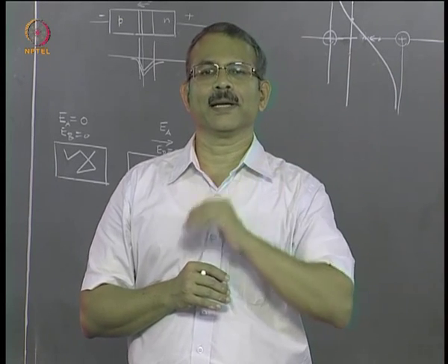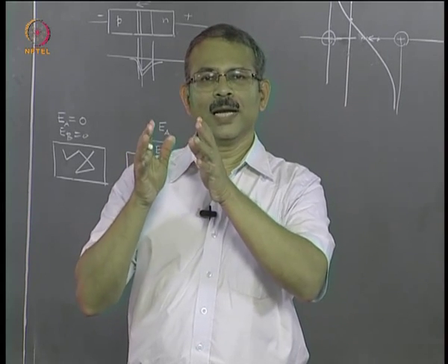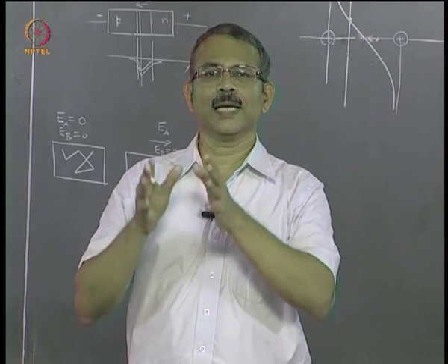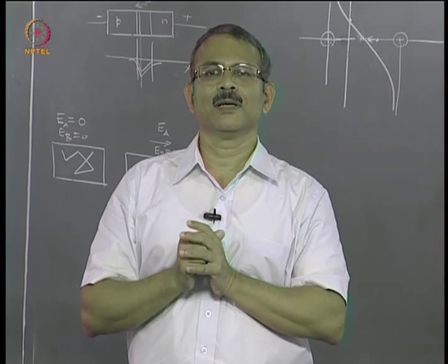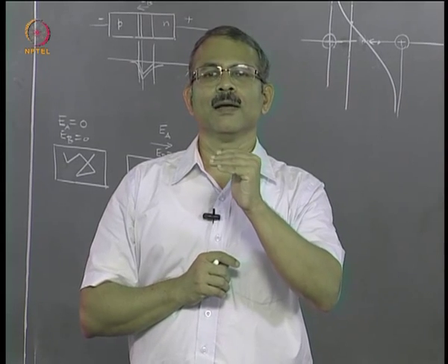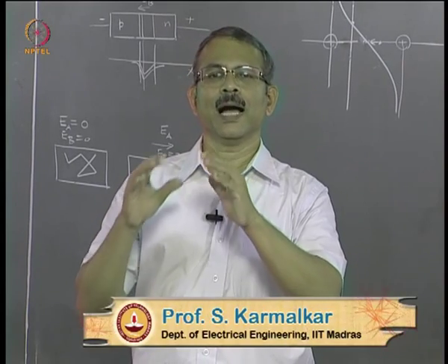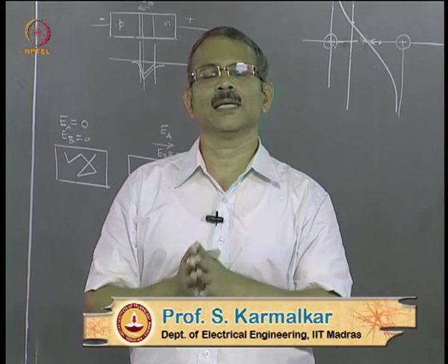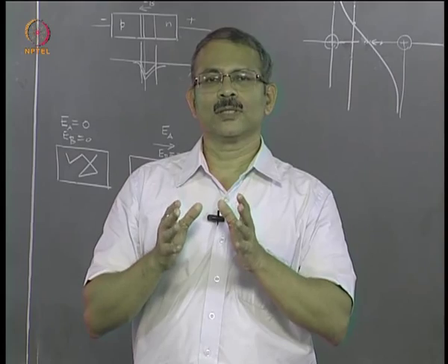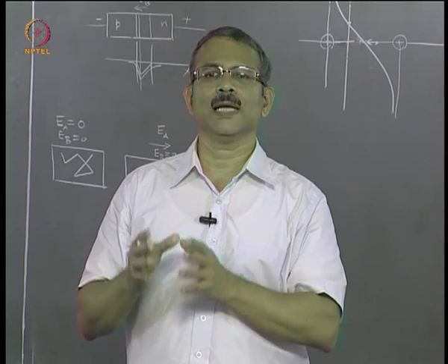Then we outlined the procedure of deriving the device current and carrier concentration in the individual carrier viewpoint, assuming the carrier to be a particle. And we said we will do a similar exercise for the individual carrier viewpoint regarding the carrier as a wave, and we just began this discussion and introduced the Schrodinger's equation, which is a fundamental equation in this particular approach. We showed that the Schrodinger's equation can be regarded as a conservation or balance equation which talks about the balance of probability, and it can be shown therefore to be of the same form as the hole continuity equation. Now in the next lecture we will discuss the Schrodinger's equation for electrons in a semiconductor and also the solution of this equation and how to derive the current and carrier concentration.